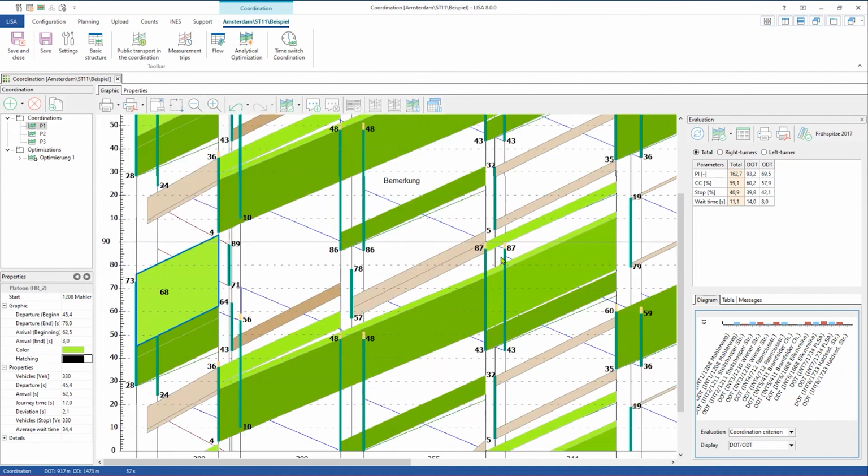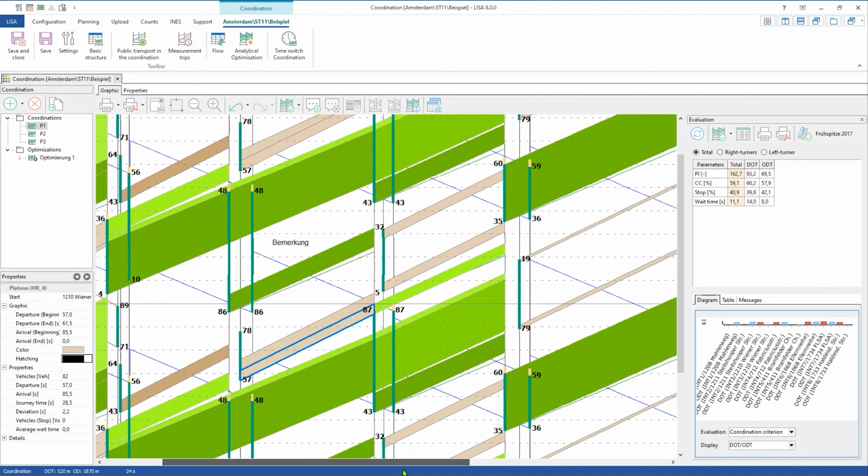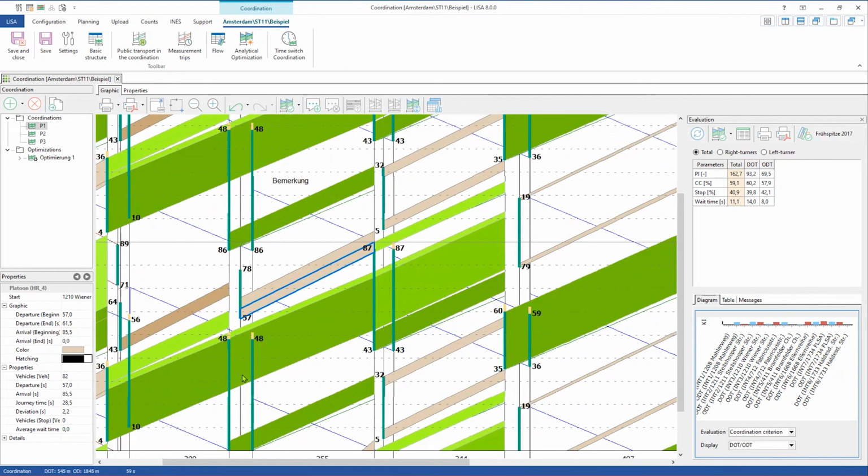So you can now track these platoons through the whole coordination module. And the cool thing is that we now also keep the minor directions in our calculation. For instance, here they are depicted in yellow, orange, or brown maybe. This minor direction starts here at this intersection. You can also say it's not a protective turn, that means a green beginning. This car starts. Maybe you say it's permissive, so they start at green end.